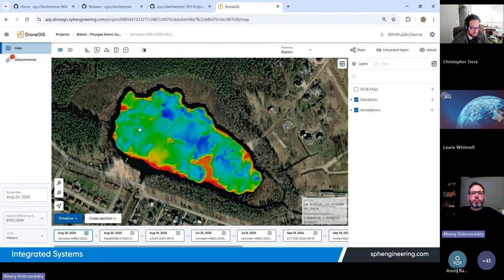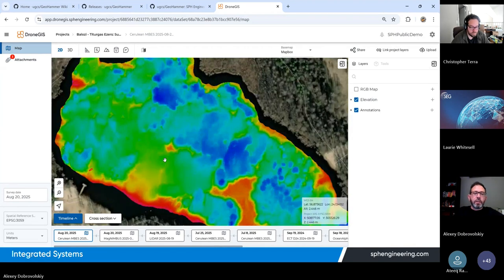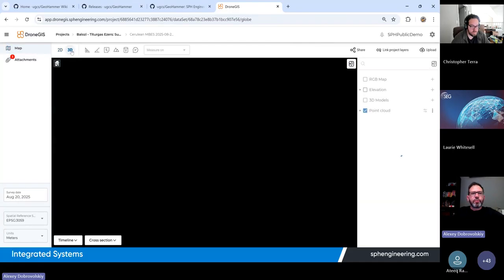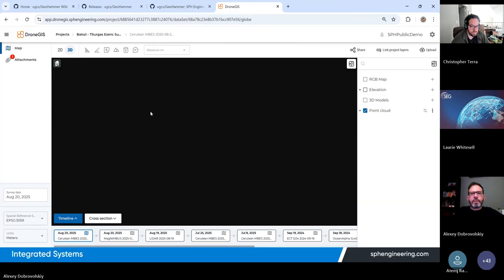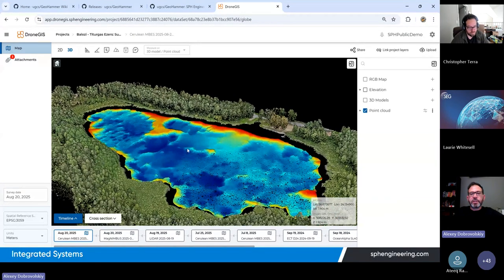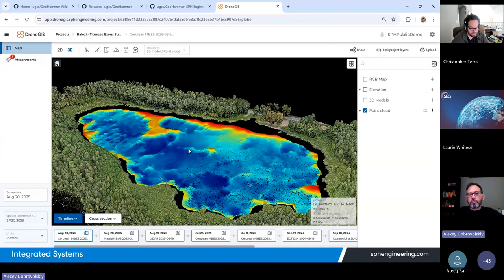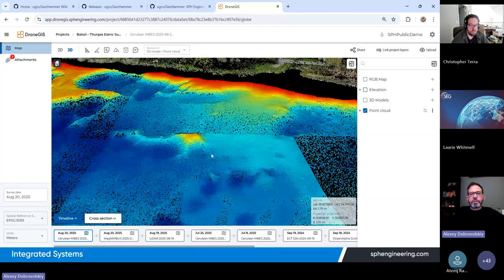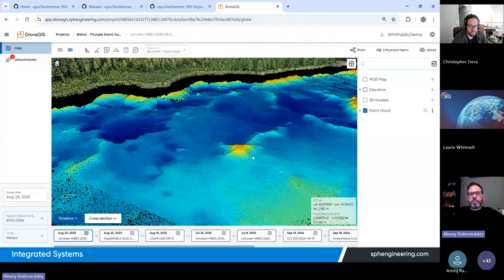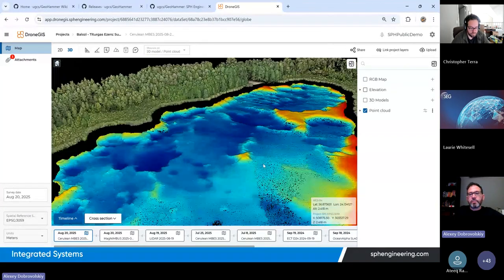Here we did a full bathymetric survey and found a lot of different, I would say, irregularities on the bottom. In 3D, it is much more obvious. And that ignited my interest because about almost every second lake in Latvia, there's a legend that here is an airplane or tank from World War II. So such places on the bottom look interesting, and we decided to conduct a magnetic survey here too.